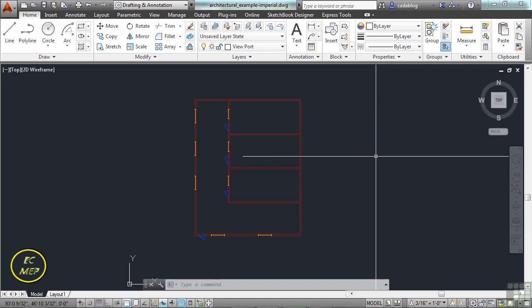What does that all really mean? Well, that bit of information that I just gave you just discusses how AutoCAD handles frozen or off layers. It used to be a real big deal back when we worked in AutoCAD in DOS, and your processor just took a long time to generate on your screen all of these lines that you had. You would turn things off or just freeze them instead because it just handled it differently. It didn't process them even though they weren't there. Well, that's not as much of a case now. Our big processors with our tons of RAM in them can handle these things.